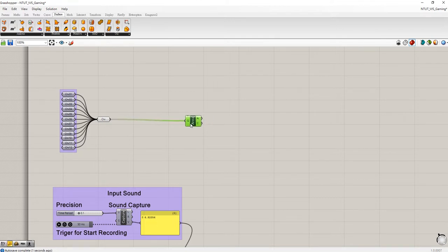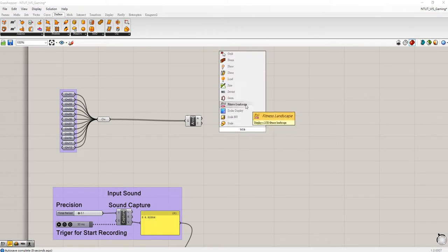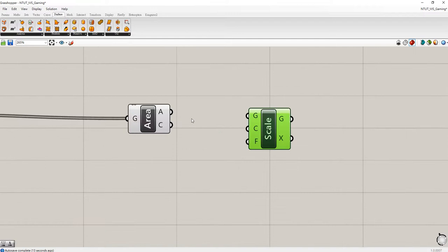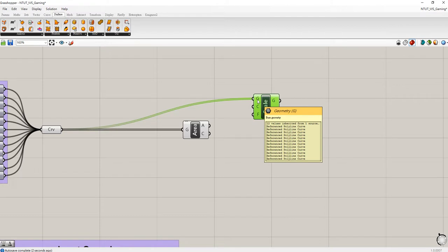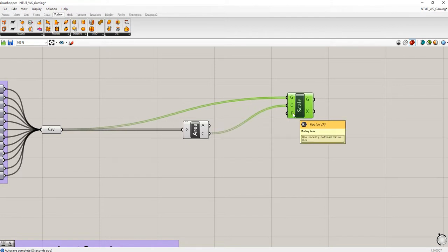First, let's go to mesh or a surface area. Put your curve inside, and you will extract the center point. And second, go to scale. I'm on scale right here. Alright, and the geometry is the curve for sure. This is to input the geometry you want to scale up. And this is the center point. And finally, about the vector.